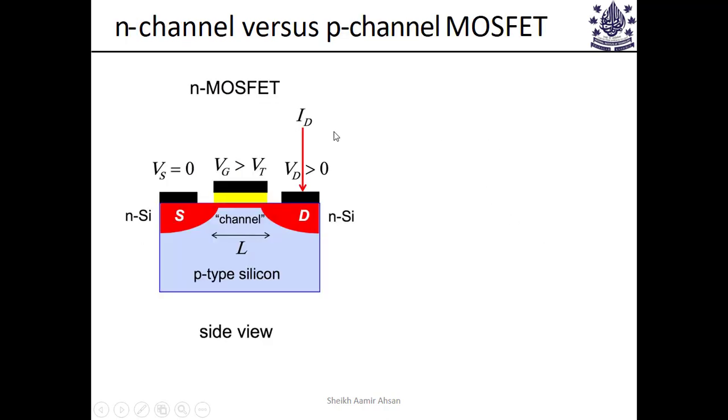Okay, now going back to the initial cartoon on n-type MOSFETs. So this is an n-type. Why? Because the channel that forms that sustains current here is of n-type, or electrons, right? So the source sends electrons, and those electrons reach the drain, and within the channel it's the electrons that carry the current, even though the substrate is p-type.